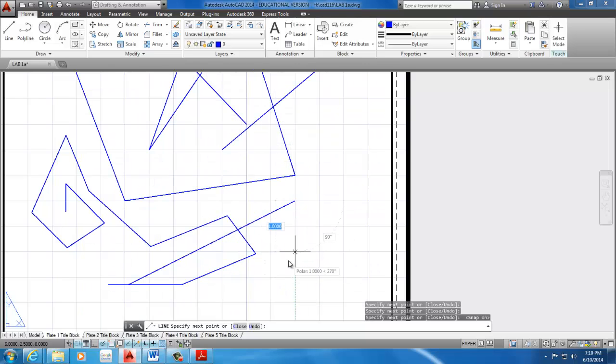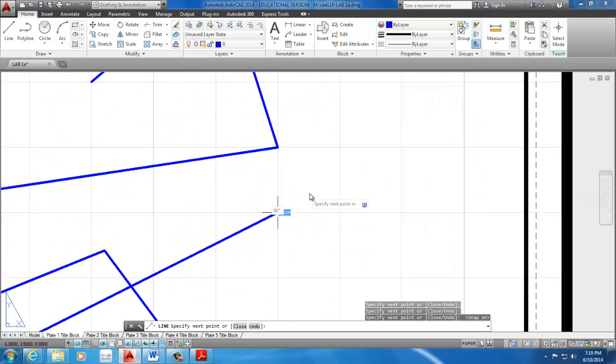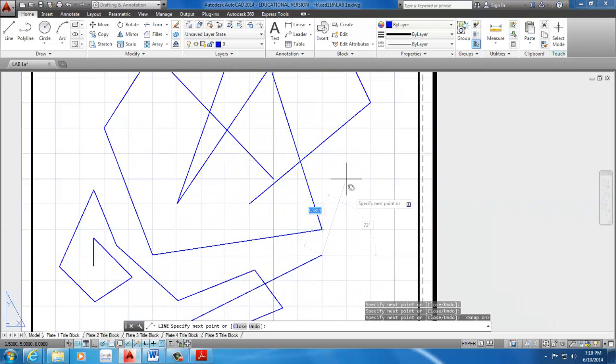The cool part about AutoCAD is it actually specifies things on where your mouse is. There's a polar, so it specifies what angle you're at, and so forth. And also specifies your coordinate system here on the left, which is X and Y. Also specifies the distance at which point you're snapping. Some ½ inch, 1 inch, 1.5 inches at 90 degrees, and stuff like that. Your 0 degrees, ½ inch, 1 inch. So you get all this information, which is maybe very useful, especially if you're doing tool and die, right? 0, 0.